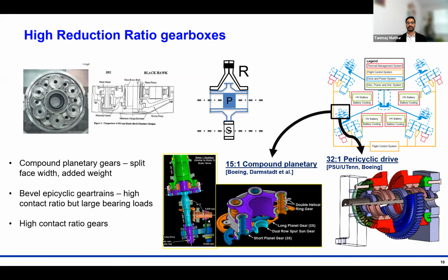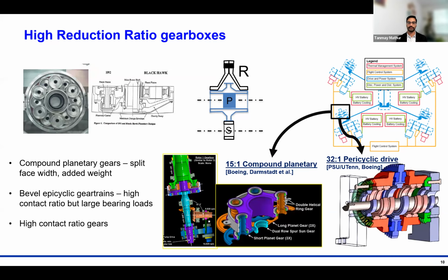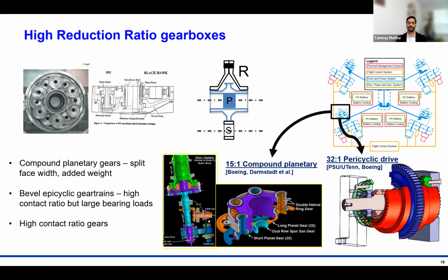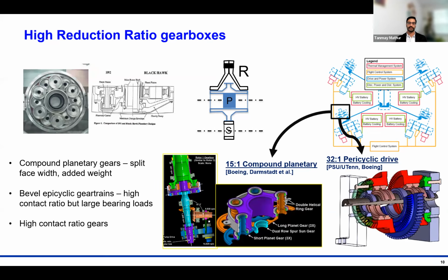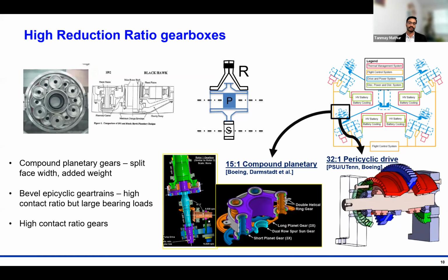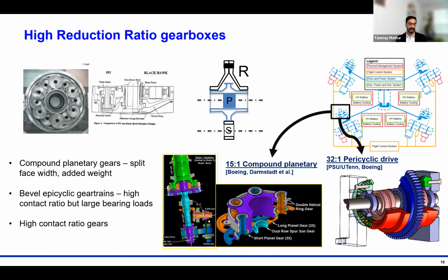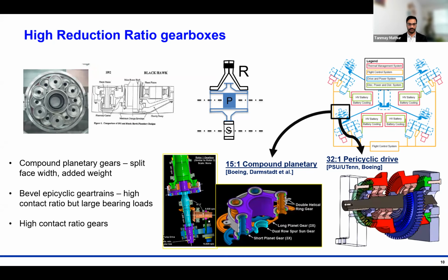So this allows you to eliminate some of the stages, right? So going from a 3-stage gearbox to a 2-stage gearbox is made possible by using a high reduction ratio. And it allows you to also use a smaller high speed motor if you intend to use electric power with a very compact gearbox, providing a high reduction ratio for the rotor stage.